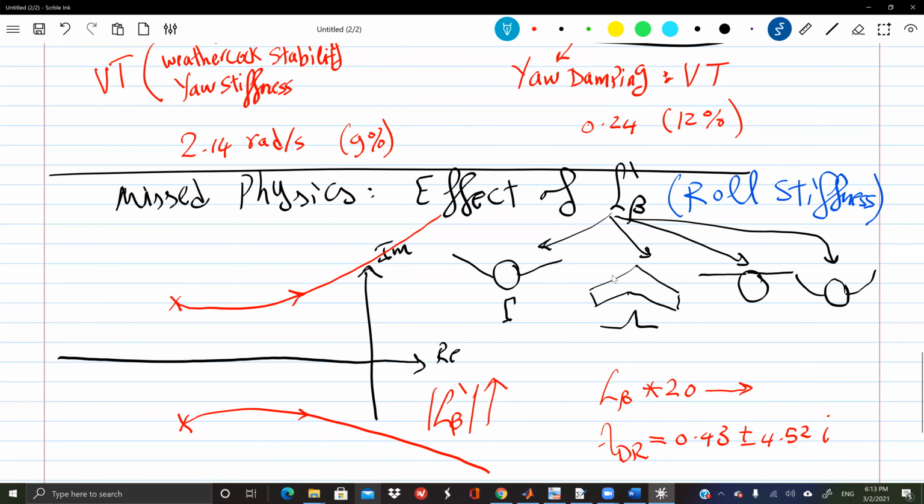this sweep is very desired from an aerodynamic perspective. If you go and study aerodynamics, you know that any airplane that goes into transonic must have a sweep to delay the drag rise. So this is something that we don't have any choice over. The aerodynamic designer will always do it. And you know that this is also something that we don't have any choice over. This is actually inevitable. This is nature, right? So we don't do anything with this.